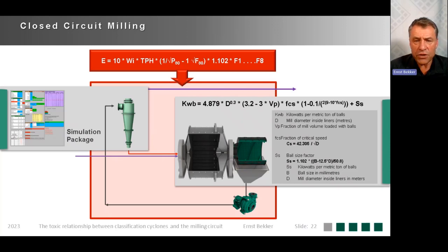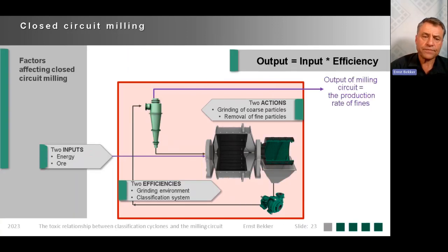If the size distribution gets into the mill, it has a certain breakage function. If you then go to the cyclone, it will produce a certain size distribution back to the mill. Now the feed size to the mill has changed, and the breakage size distribution needs to be re-altered or recalculated. This is a very complex calculation process. So most of the applications that we as suppliers are involved in revolve around getting a mass balance and selecting the cyclone. And in that mass balance, the grind has already been specified. So we are using that as our reference.